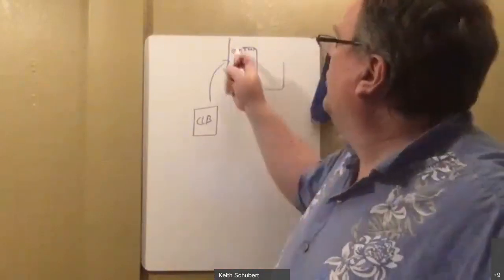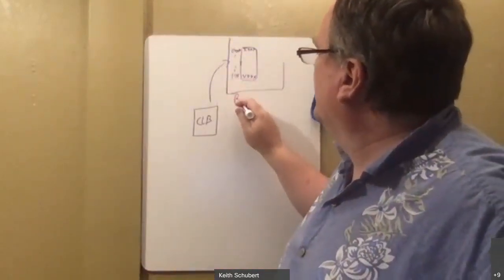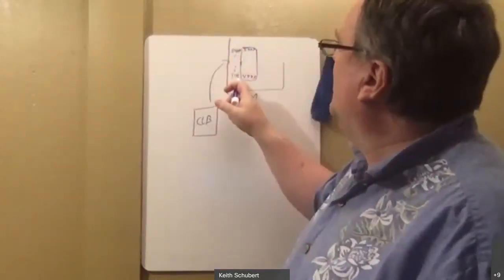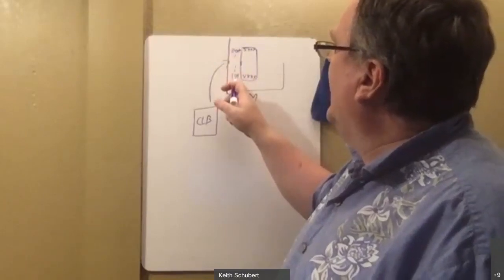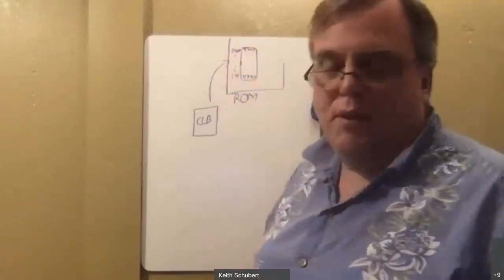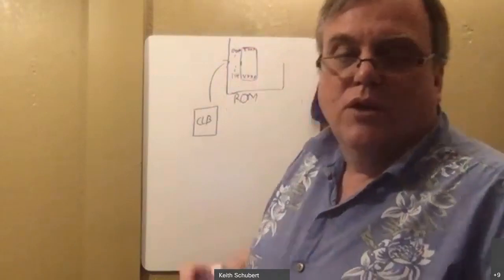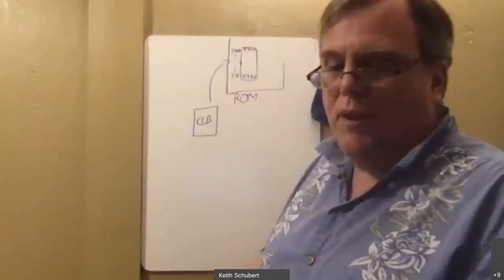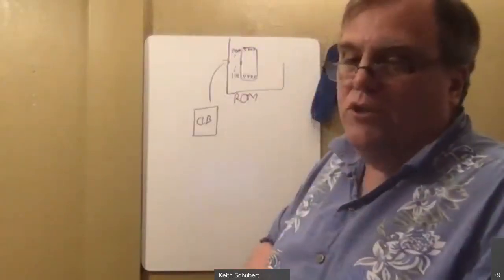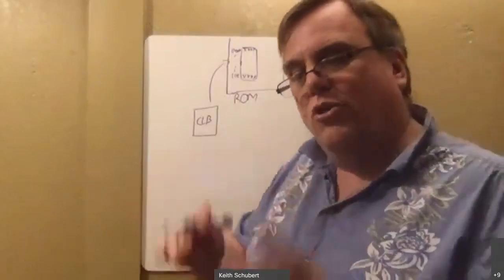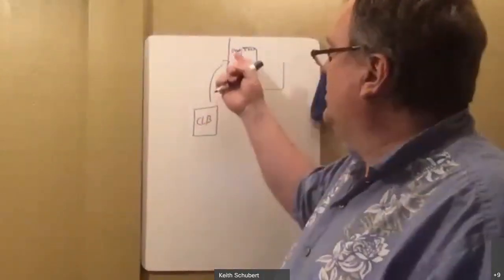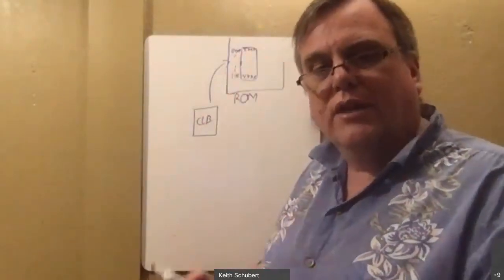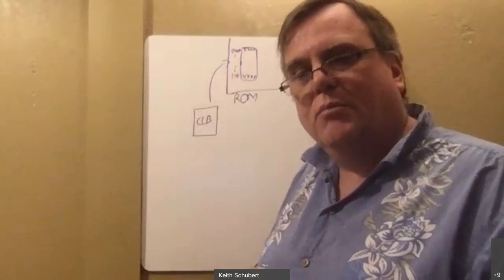This style of thing, and we'll talk about this later in more detail, is called a ROM, because basically your inputs become addresses and your outputs become the memory that's stored at that location. So they're called lookup tables or ROMs, based off the old read-only memory. When you're programming your thing, they figure out what your logic would do for that particular address, and it just stores it as a memory location. So this is the way that your logic is actually implemented.